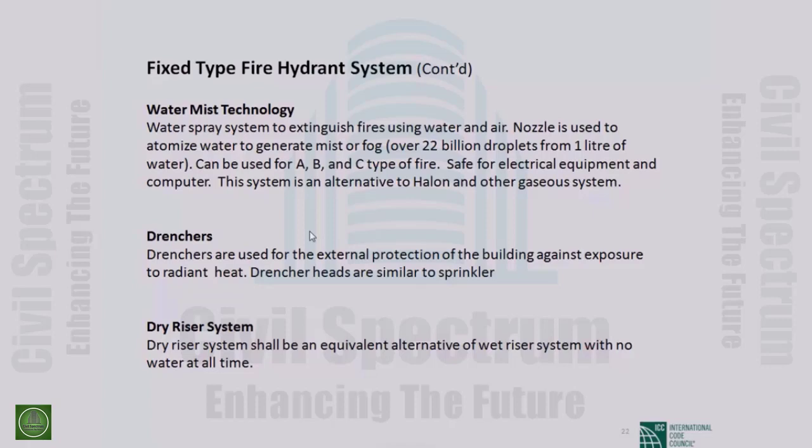It is a special type of drenching system which will be kept in a certain area, if you would like to cool some wall, or some tank, as for example, if we have a generator, if we have a big fuel reservoir, to control the temperature of the fuel reservoir, sometimes you need to cool the surface of the liquid fuel tank.